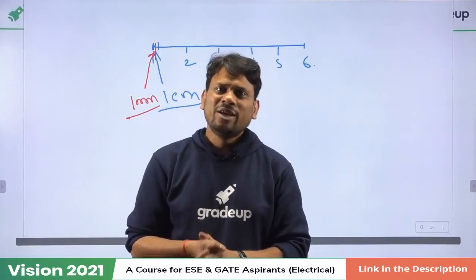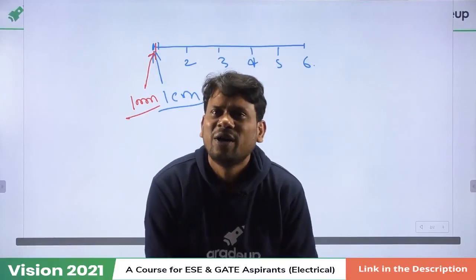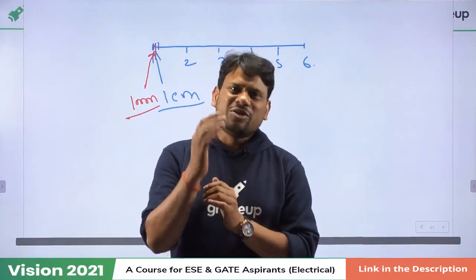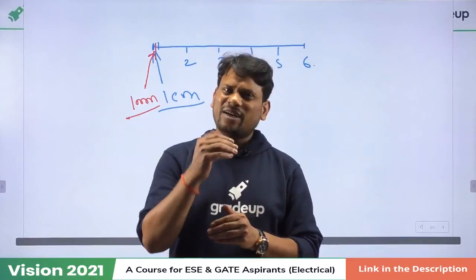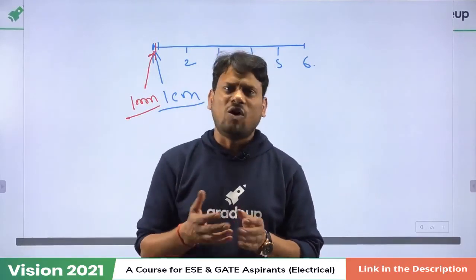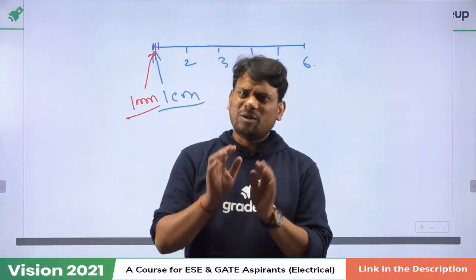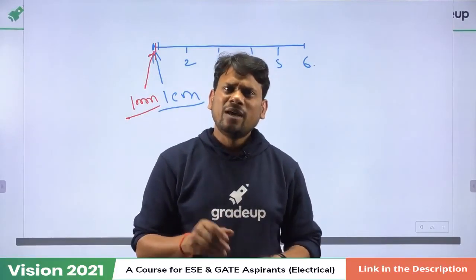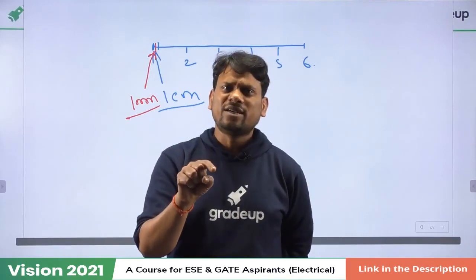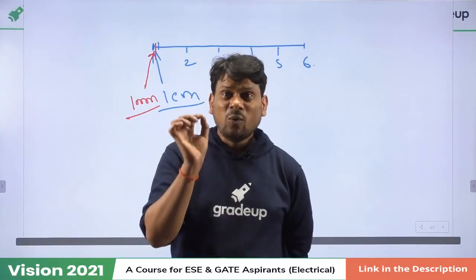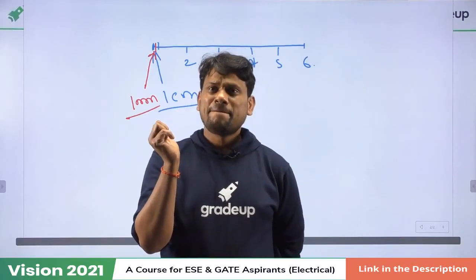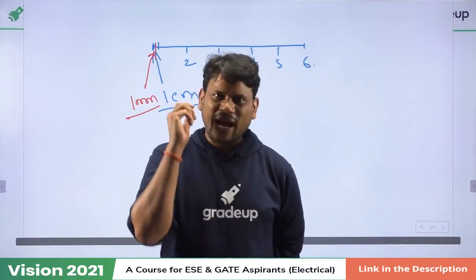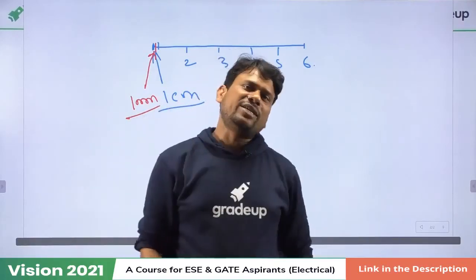Or any other branch. Okay, so now we are going to discuss some formulas. Please try to understand. Now we are going to discuss some formulas related to multiplication, subtraction, addition or division terms. We know that we are not supposed to waste our time on this analysis, but just try to understand, dear friend. When we add two or more quantities, listen to me carefully, we have to add absolute error directly when we want to add or subtract two or more quantities.